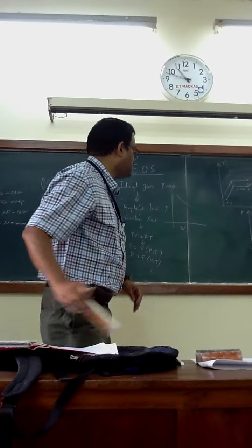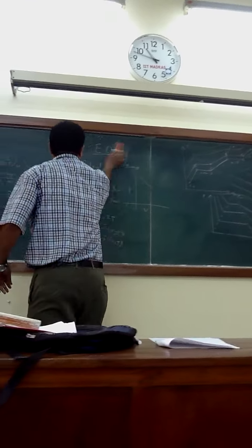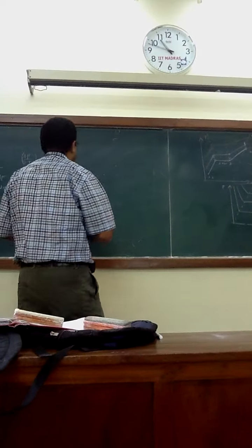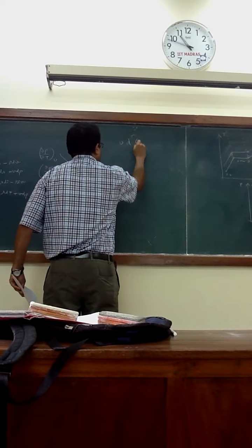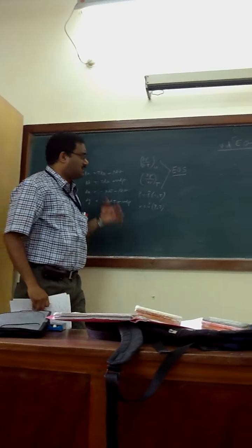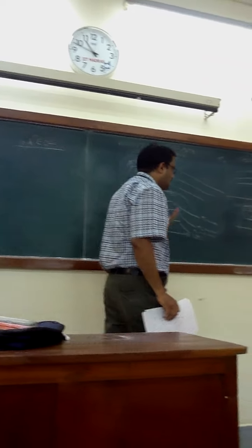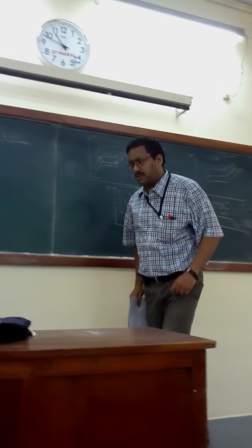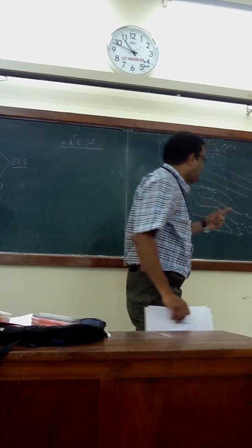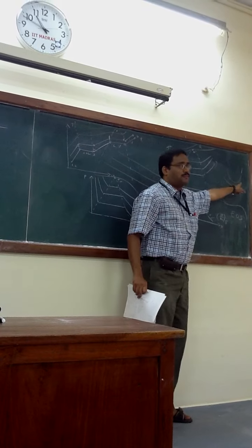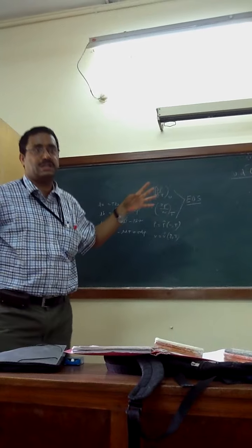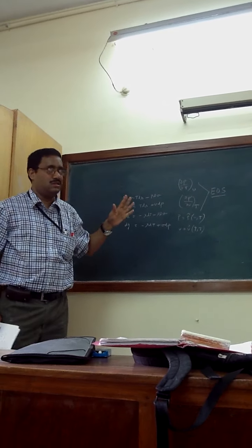The first fundamental equation of state is the van der Waals equation of state, VDEOS. First I show you the form and you see that it is exactly cubic form. Otherwise you cannot. One cannot have a quadratic equation of state, because we need to have two curvature changes, and with that we cannot predict the entire behavior of the liquid to gas for the temperature range.